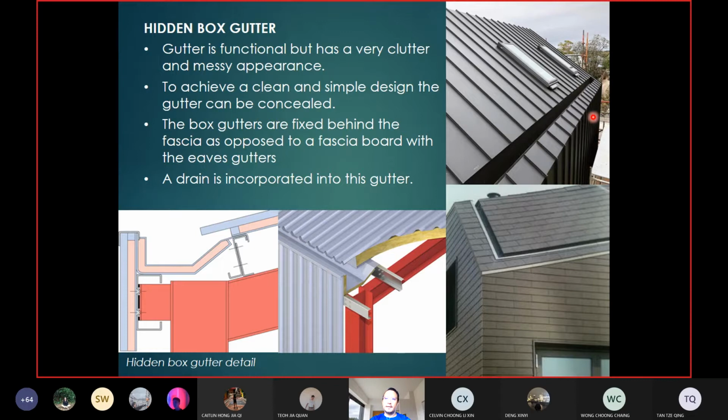But in the Malaysian context, normally if you have windows and your roof overhang is not deep enough, or you don't have a roof overhang, then water might splash into your window, things like that. So that's another thing that you need to consider. If you want to use this, you need to consider whether a roof overhang is important for your design, or for the site or not.